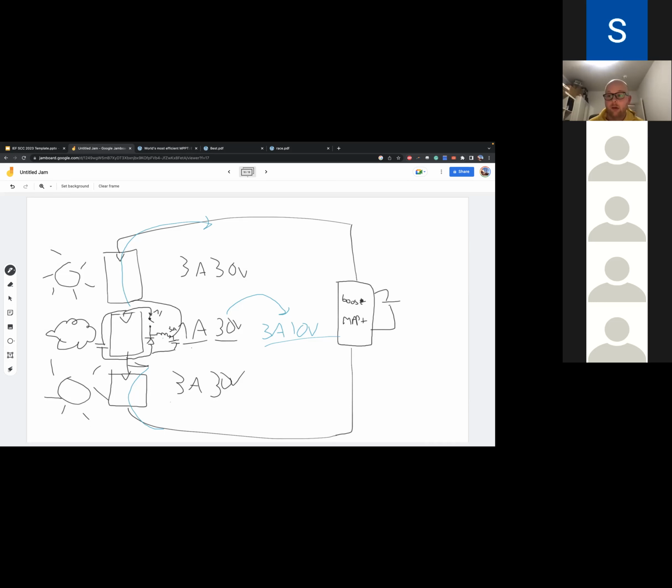And then because the diode is on like 66% of the time, this is like 2 amp on average. It all works out. If you run the numbers, this all works out and you get all the power from your array. And this wins you like 30 watts when there's shade, because otherwise it would be 0 volt and 0 watts on the middle one, and now you get 30 watts.